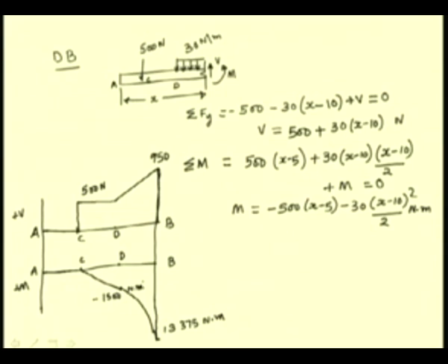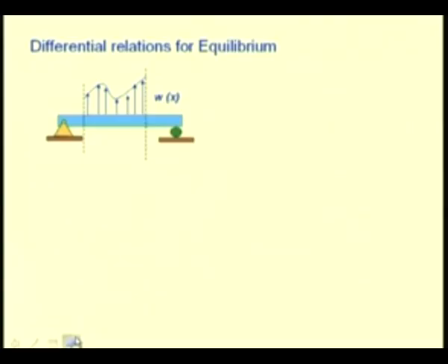So, in this way we can construct the shear force and bending moment diagram for beams with concentrated or distributed loads. For the distributed force, if we consider the differential relations of equilibrium rather than the algebraic relations of equilibrium, the construction of shear force and bending moment diagrams becomes easier.